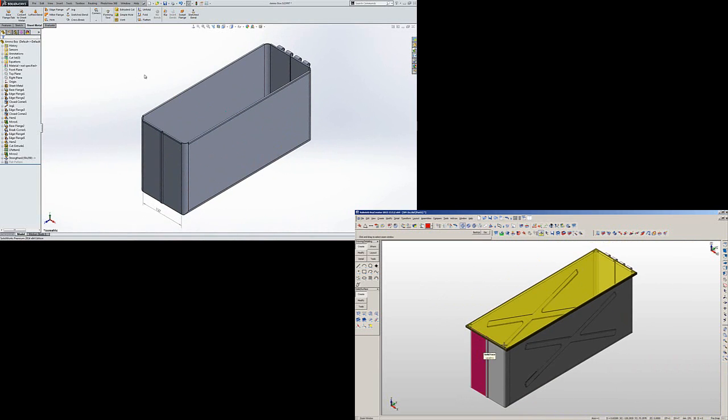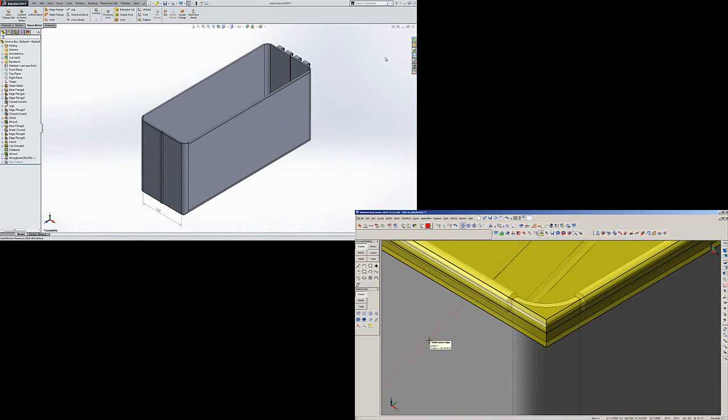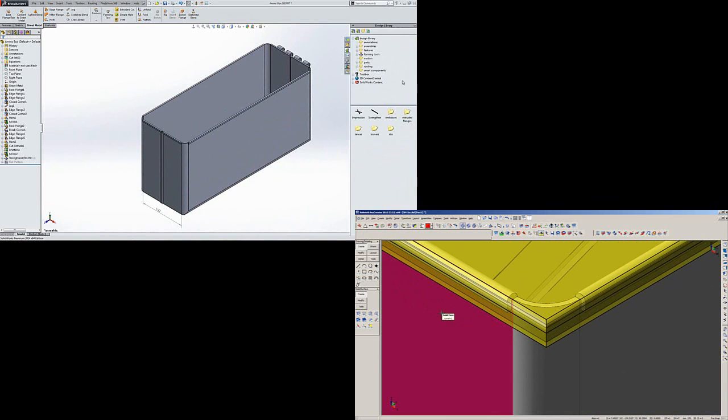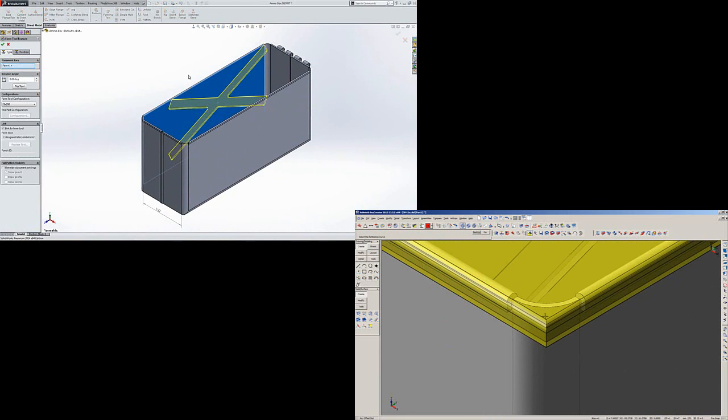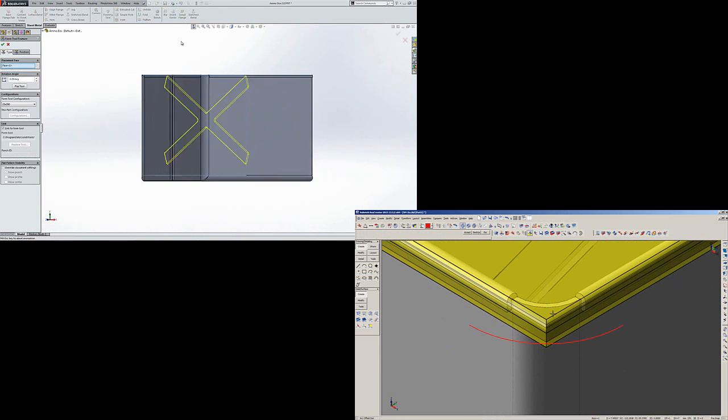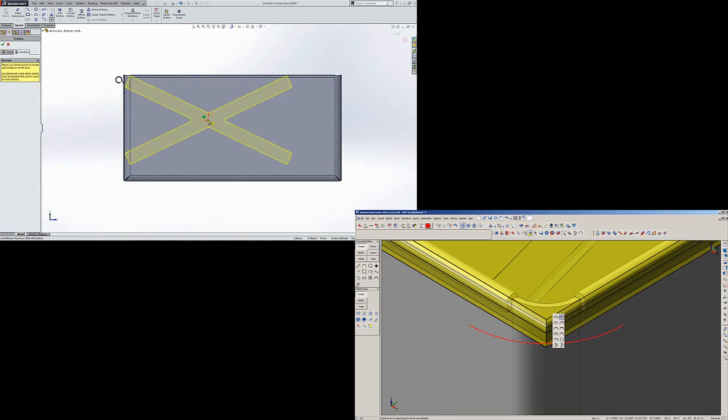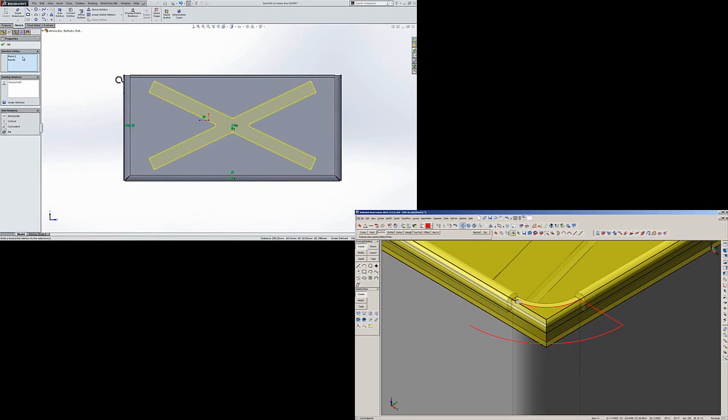So the next thing we can do is mirror another impression. I'm just going to drag an impression on this side here, and we'll go normal 2, and adjust the position of that. Like before, I'm going to select the midpoint and the origin and make it vertical. Same on this side. We'll make it horizontal. And that's actually perfect now.